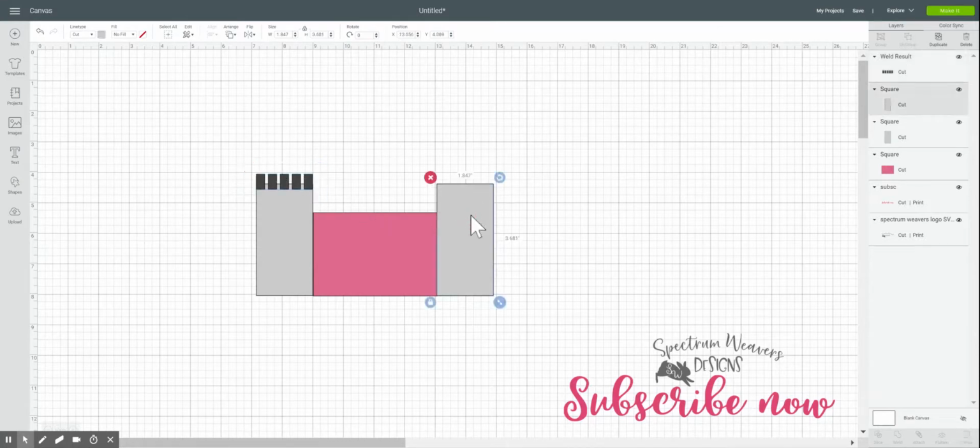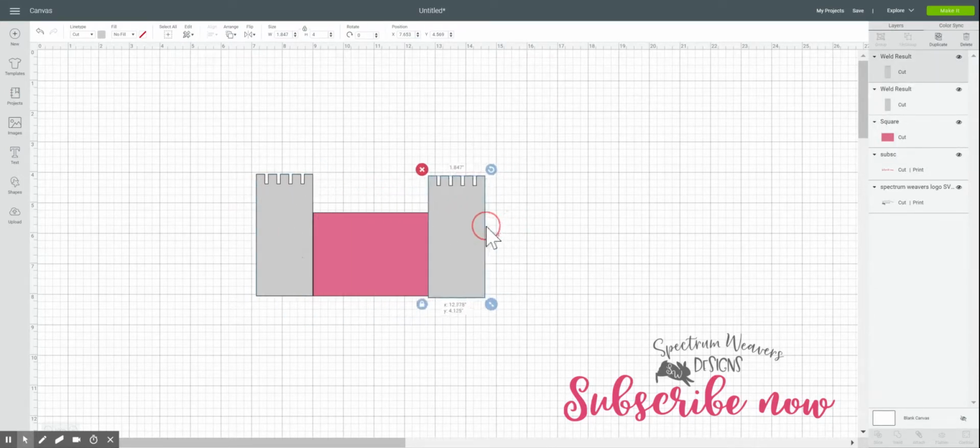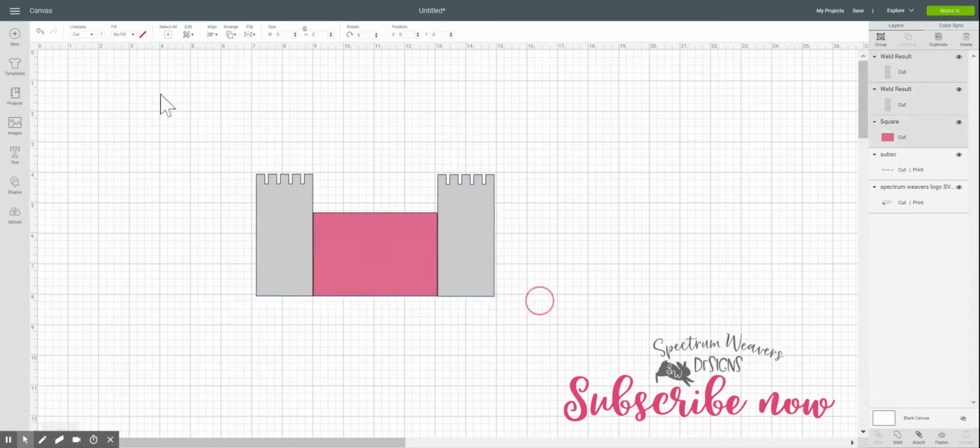So what I'm going to do, I moved too quickly on that. I shouldn't have made this one because I'll just duplicate this. I'm going to select the tower and the top shapes, and then weld those all into one single piece. Okay, that's now one piece. And now I'm going to select that and duplicate it. Okay. And I'll move this right over here. And again, I will select the three of them, and I will align bottom. Okay.